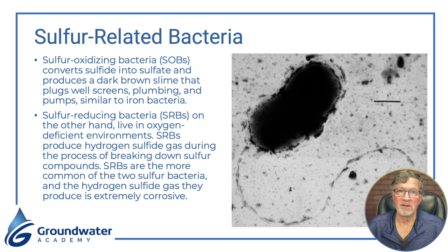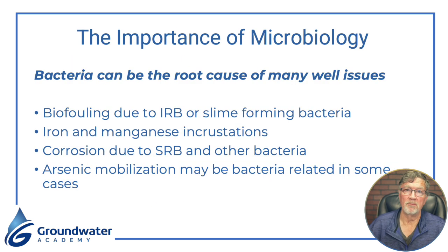Now, the interesting thing: they're anaerobic bacteria, but they can actually grow under the biofilm produced by the iron-related bacteria where there's no oxygen under there. So you actually get a consortium of bacteria growing. So it can get very complicated. That's why it's important to properly assess the well so you know specifically what you're dealing with there.